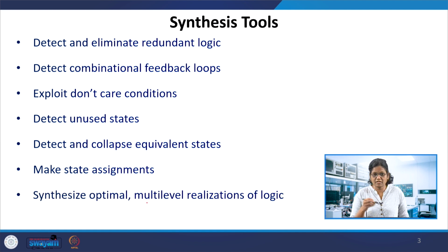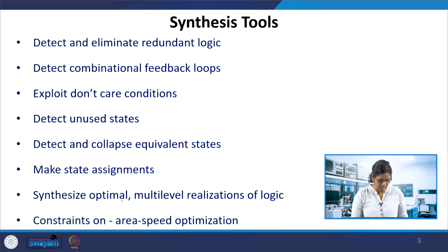It synthesizes optimal multi-level realization of logic. The logic which is given may have multi-level logic, but that needs to be optimized by considering the constraints of area and speed. So area should be minimized and speed should be high. This optimization needs to be taken care of while doing the synthesis of multi-level logic realizations. Especially finding redundant feedback loops, handling don't care conditions, checking whether there is any unused state, or whether any state minimization is required. Those things are dealt with by the synthesis tool.